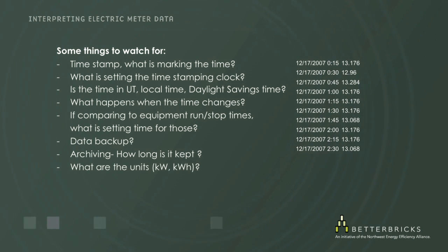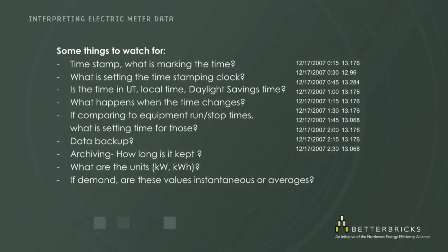Are the units in kW or kilowatt hour? If it's a demand in kW, are these values in instantaneous demand? For example, a lot of weather stations will take the temperature and they'll take it 3 times an hour, but they may report the temperature as being the highest during that hour, or they may average all 3 readings together. So the same thing with energy usage. You need to know, is it instantaneous value? You sampled it at 12 noon and that's the value you're using.